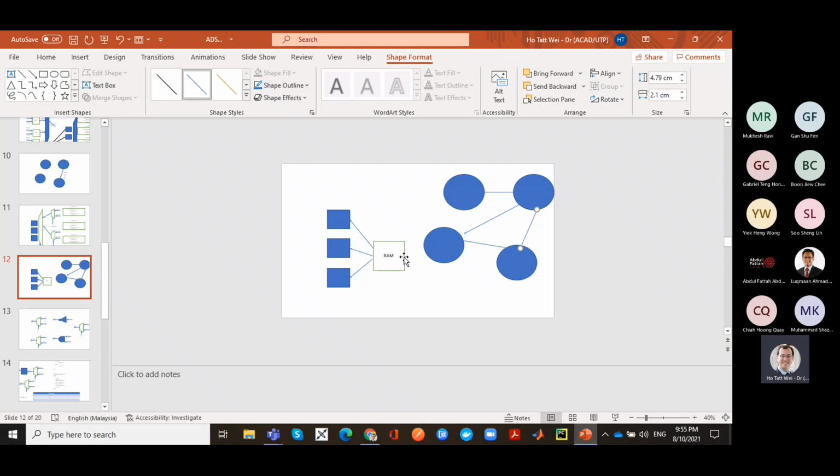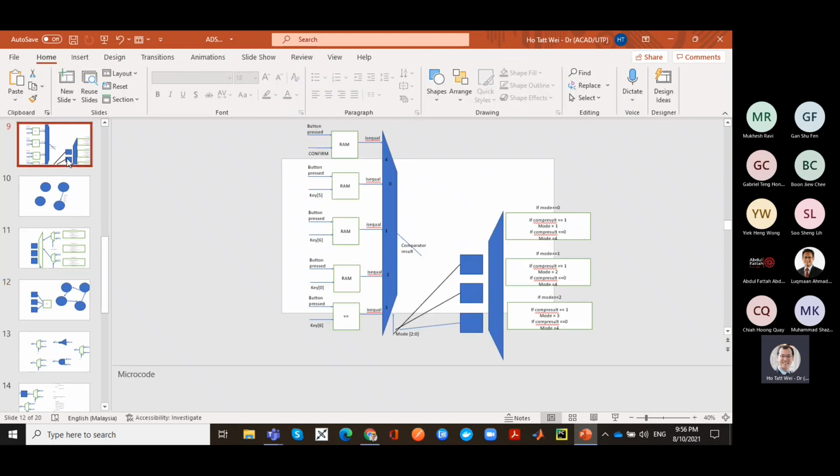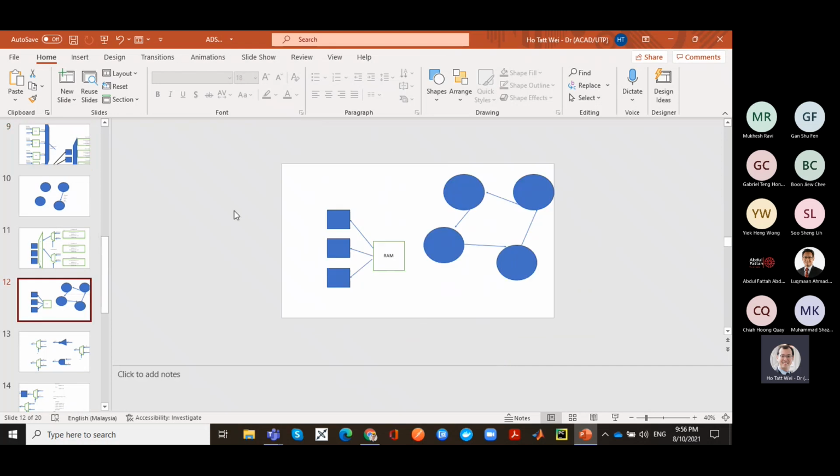So if I were to change the programming of the RAM, I can implement a different trajectory of states. Basically, I can actually do the opposite. I can start from this state going to maybe this state, going to this state, going to this state, right? So all of a sudden, it opens up this concept that, hey, not just this idea of lookup tables, not just I can implement changes or be very flexible with the type of computation I want to do, I can also reprogram the sequence of state transitions.